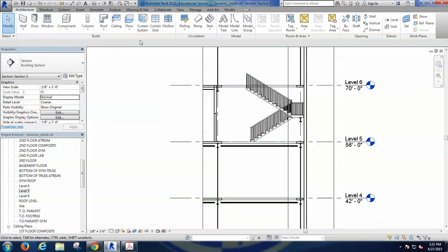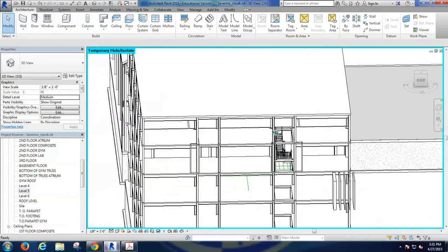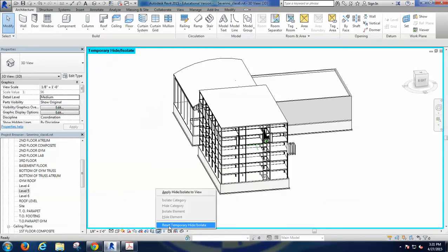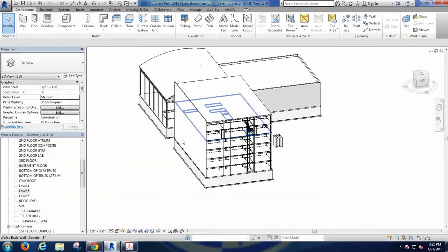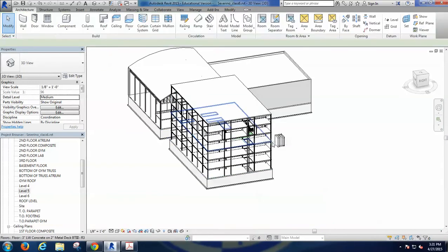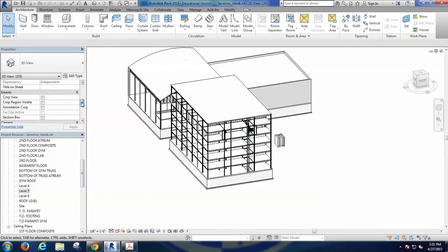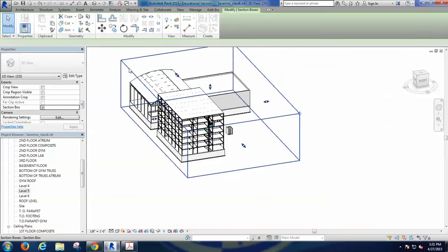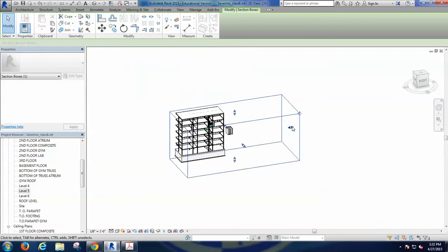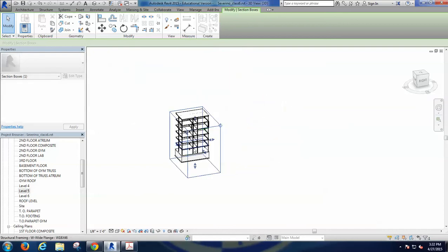the shaft. I actually like to do this shaft fixing from the 3D. Better safe at this point. And I like to turn on, let me reset this, I like to turn on the section box and work on the section box for the stairs, because you have to deal with both vertical dimensions and horizontal simultaneously.